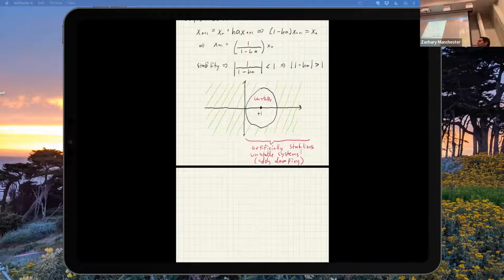They use this, and they also like to take big steps, right? The simulators like to try to take big time steps because it's more efficient, and your controllers typically are not running at super high rates. So in order to make things not blow up and not look stupid, they just add tons of damping to the simulation artificially to make it super damped so that it doesn't blow up. They try to make it visually not look stupid and not explode on you. So they use really crap integrators. They try to take big steps and they just add lots of damping to make it not blow up.